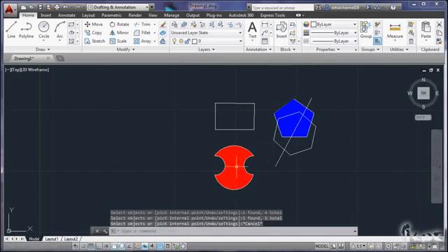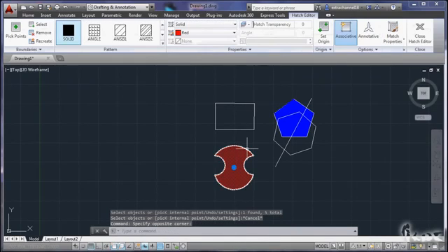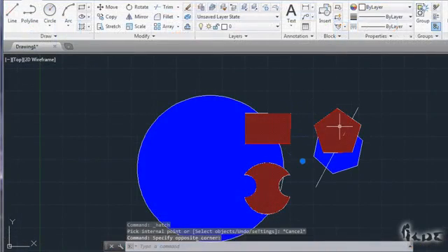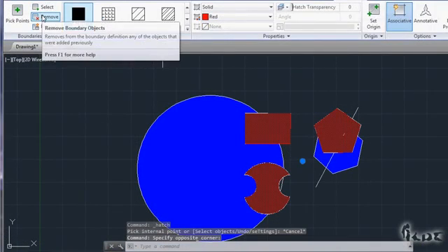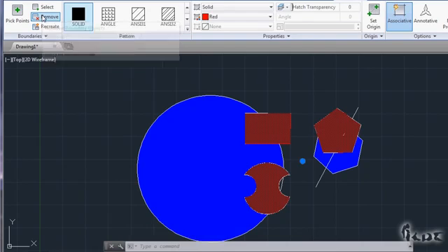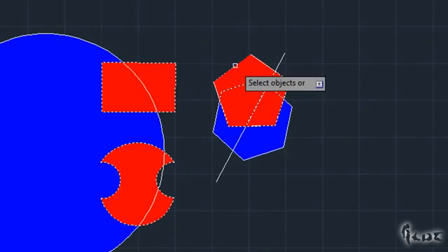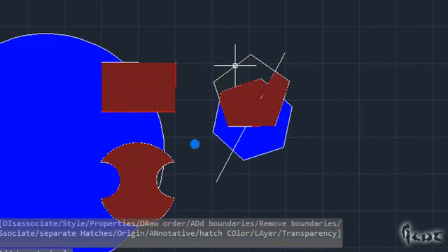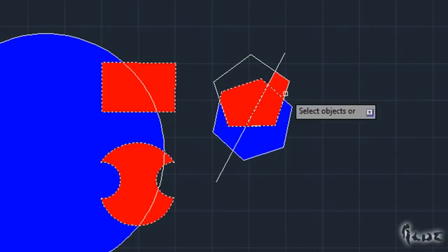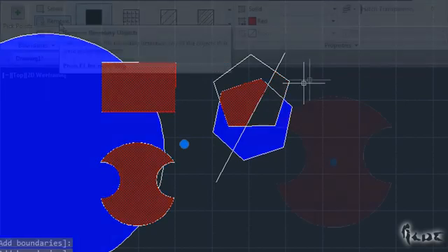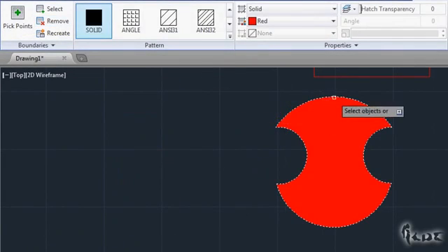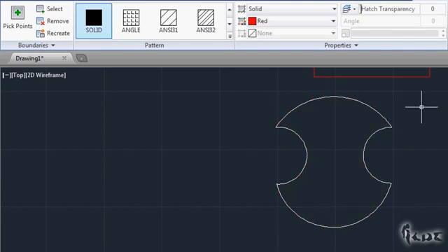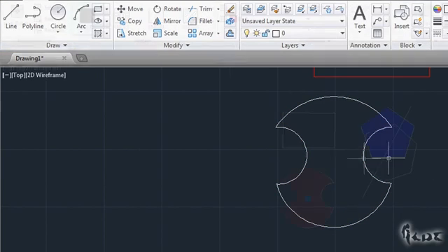Whenever you need the edge creation window, just select a pattern you already made. It will automatically appear. On the Boundaries section, you can remove these patterns too. Go to Remove and select the objects that create the enclosed area. It's needed just one side missing in the area to remove the wall edge. If you select the boundaries of a pattern aside, this will be directly removed.